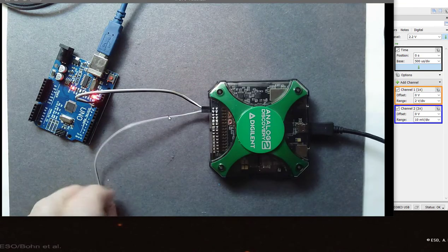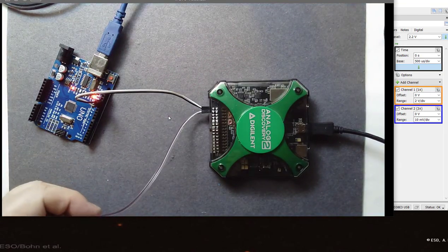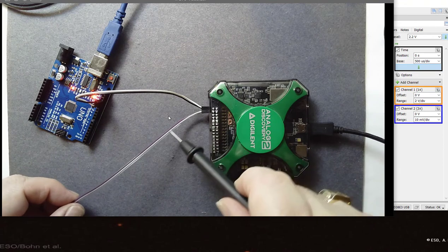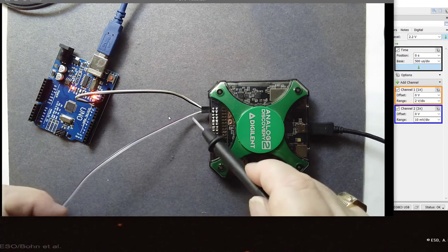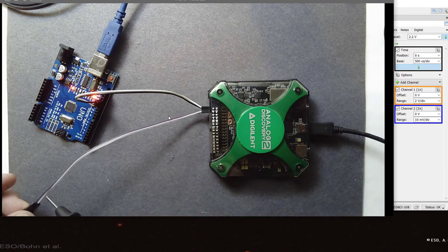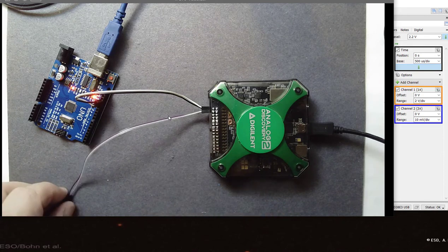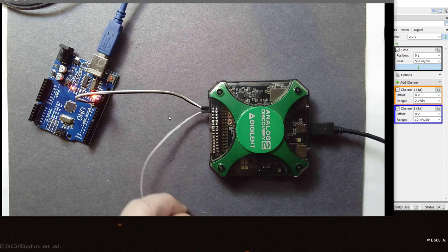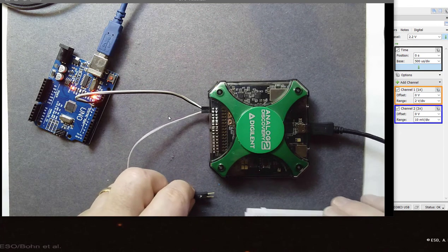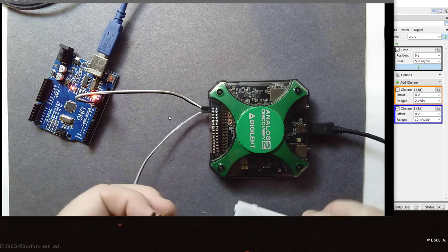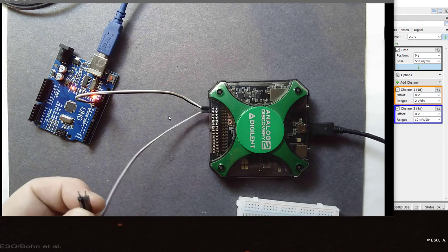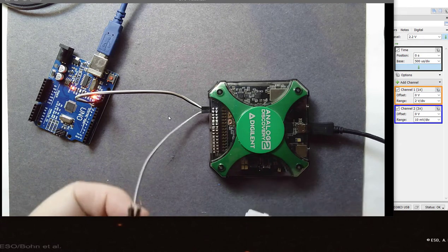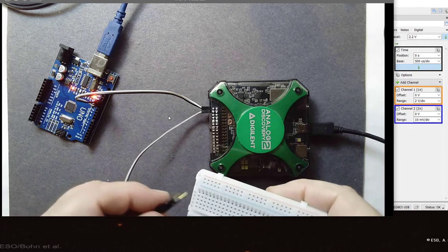So let's plug in our other loop and look to see how much inductive coupling there is channel to channel. So we have another loop in channel 2. Again, I've kept them on the ribbon cable, so I have them as tightly coupled as I can given the discrete nature of the wires. I'm going to keep the channel 2, the victim line, far away. We know that there will be capacitive coupling, and we'll see some pickup on channel 2, but I want to look at the inductive coupling.